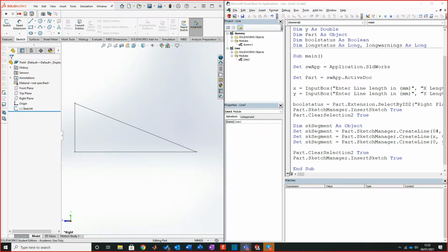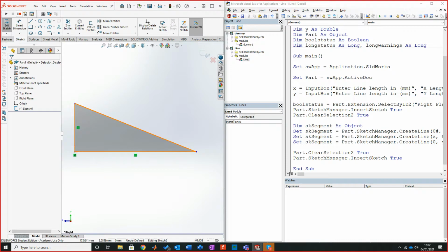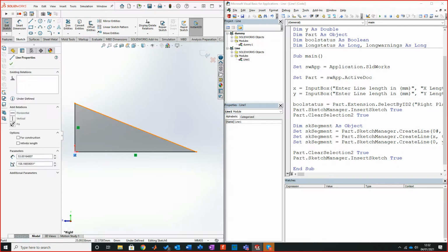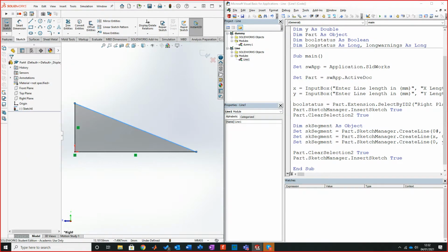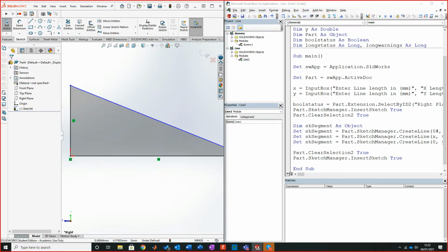The important thing about this is if I click onto here, by the way, you'll notice that it's been shaded. So these points have met. It means my snaps are on. If my snaps weren't on, these points would not be connected and I would simply be able to move this line without the others responding to it. The other thing that you'll notice as well is that this isn't defined,